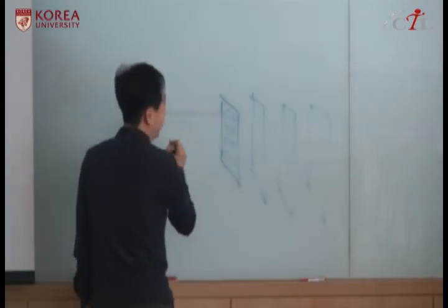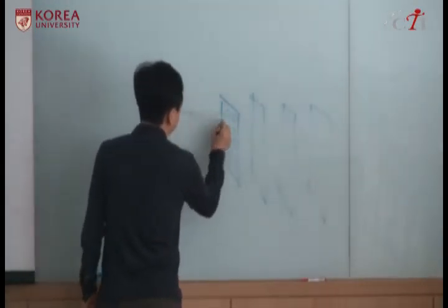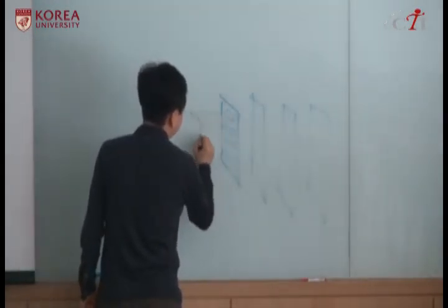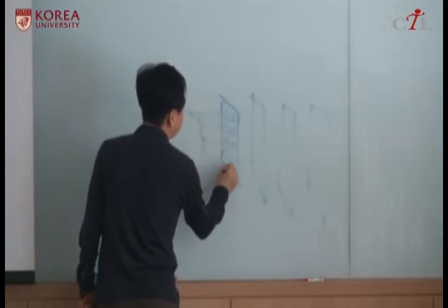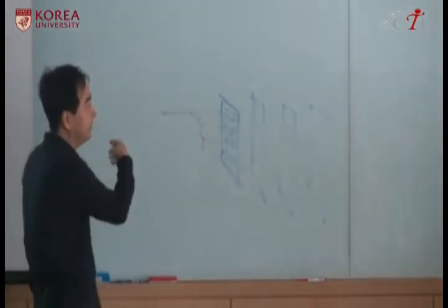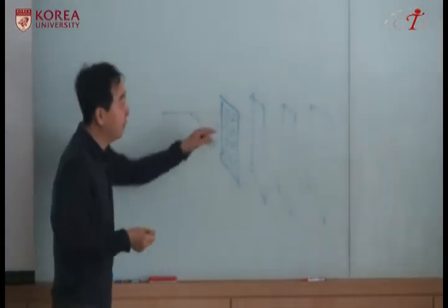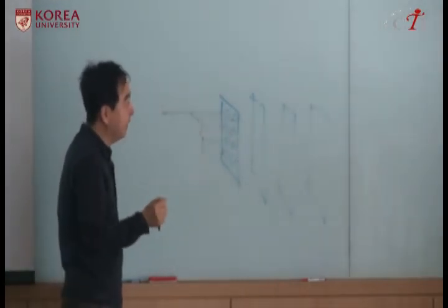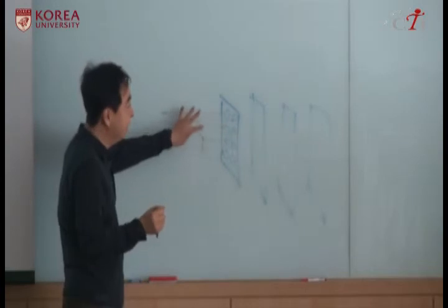Address bus line comes in here. It goes to here, goes to here, here. So 8 branches. This increases the reflection and it increases the number of loads. So it actually takes time. Okay, so this is the signaling issue.